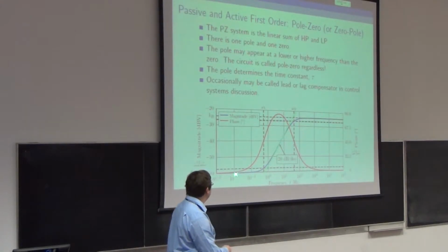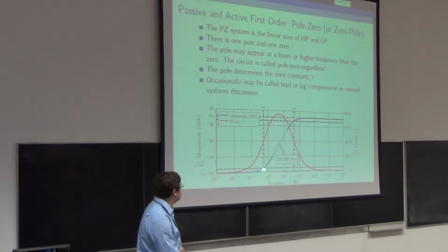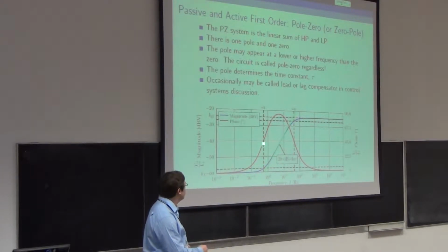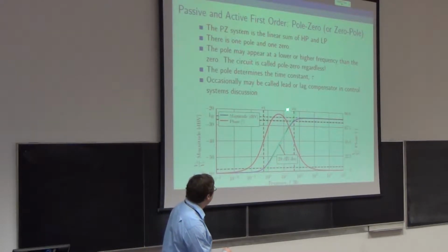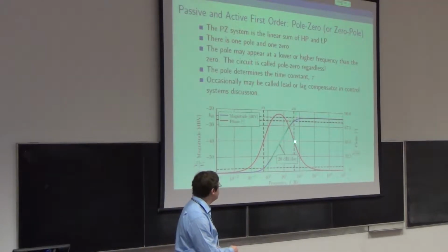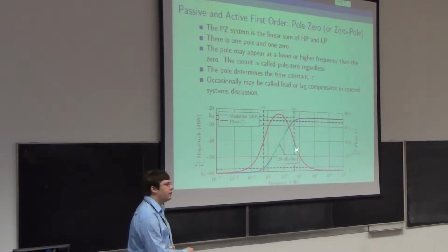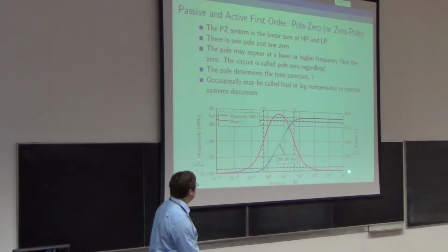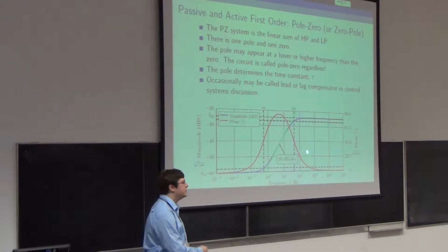And if you look at the phase shift, we have in the beginning no phase shift, and we find a 0, and by the time we find a 0 we have to have 45 degrees leading, and then it keeps going. It wants to get to 90, but before it can we find that this pole is in the way and we have to start bringing the phase back down, heading towards 0, and at the pole frequency we'll find it's 45, because it's essentially this bit wants to do that with the circuit. So it wants to give us 45 to 90 degrees lagging, but it's starting from a notional position up here of 90 degrees leading, so it takes us back towards 0.